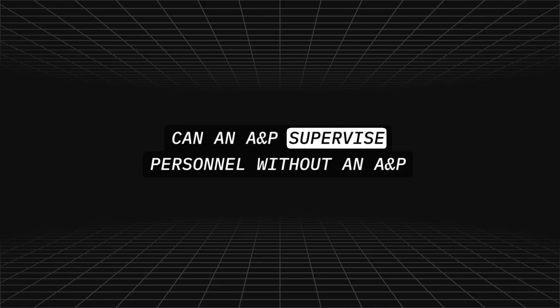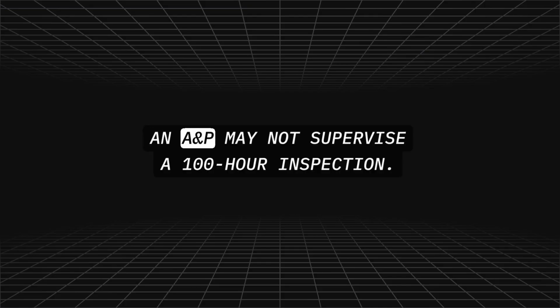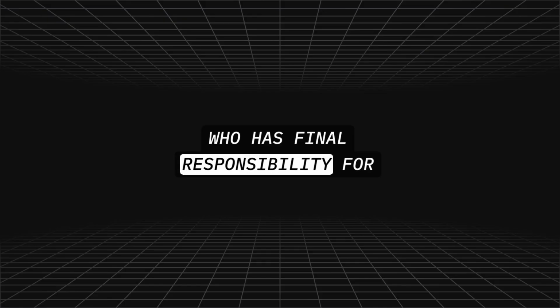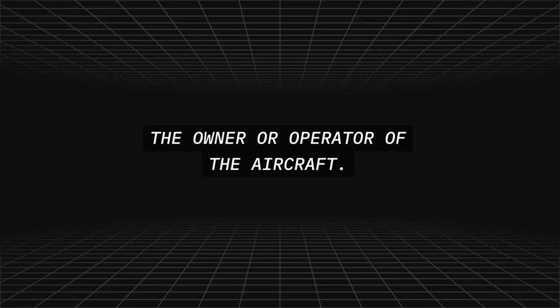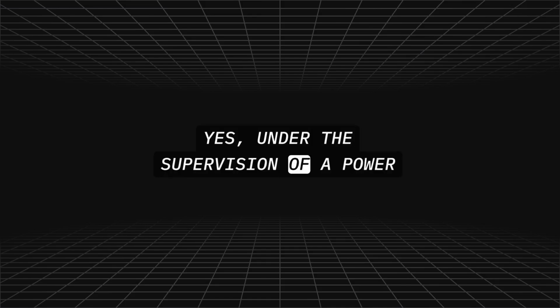Can an A&P supervise personnel without an A&P certificate in performing maintenance and/or 100-hour inspections? An A&P may not supervise a 100-hour inspection. Who has final responsibility for maintaining aircraft maintenance records? The owner or operator of the aircraft. May an airframe mechanic perform maintenance on engines? Yes, under the supervision of a powerplant mechanic.